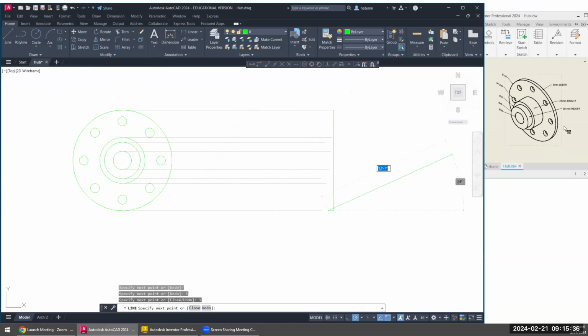Okay, so from here, we now run into this cylinder here. So we're actually just going to go ahead and go all the way up and over. And then we'll choose our line command again. There's our larger cylinder. And the larger cylinder has a height of 25 millimeters. And it goes all the way over to here. And our smaller cylinder here, we'll go ahead and start our line here. And it has a height of 10 millimeters.